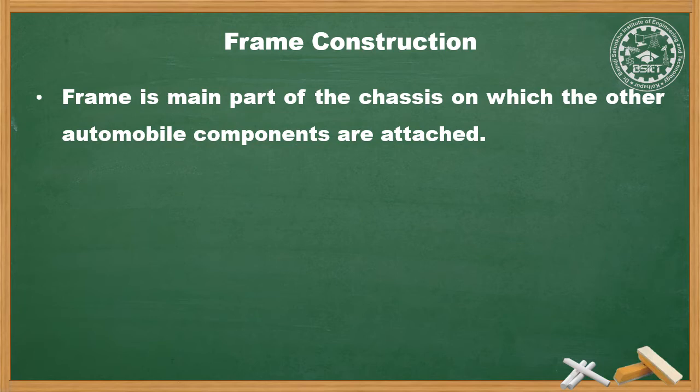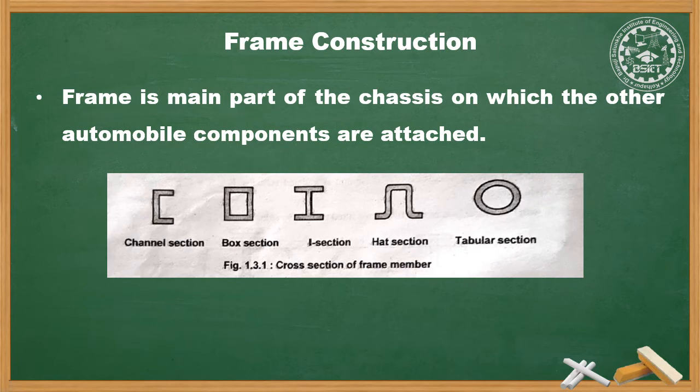The frame is usually made up of box or tubular channels or U-shaped sections welded or riveted together. Figure below shows the frame longitudinal members and cross members. The frame is upswept at rear and front to accommodate the movement of axle due to springing. The frame tapers from the rear to front to permit adequate movement of steering wheel to give smaller turning circle and steering lock.